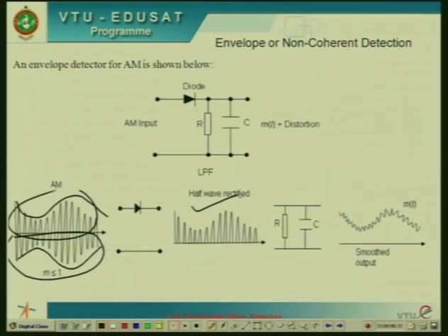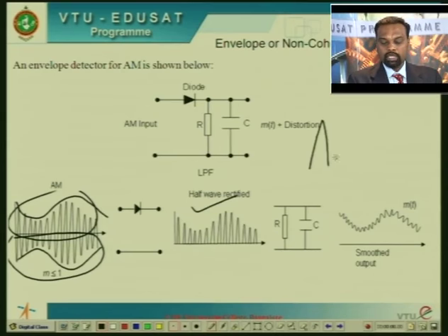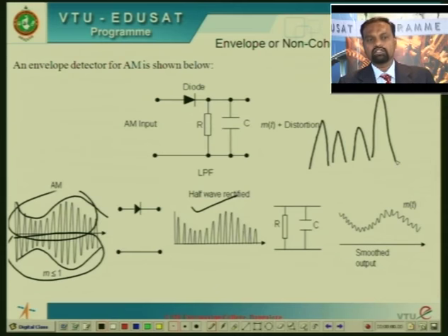And now if you try to see the positive voltage, whatever you come across, they are all like pulses now. They are all like pulses like this. Because it is a carrier signal which is actually a sine wave, only the positive half of the sine wave is taken out of the diode, and you get all these pulses. Now we call it an envelope detector because we keep tracking the envelope of this signal. What is the envelope? The peak amplitudes of the signal. These peak amplitudes we call envelopes. So that is why we call it an envelope detector.